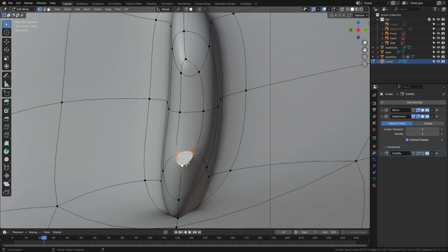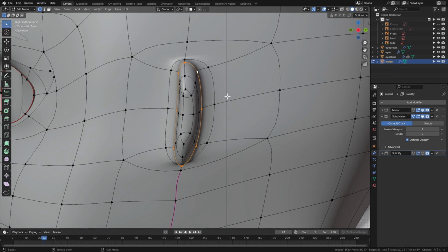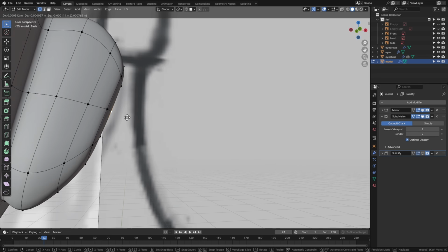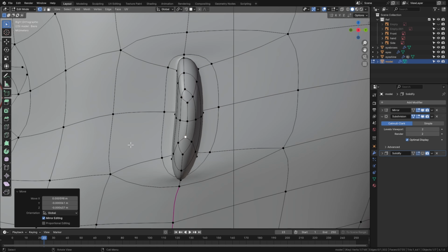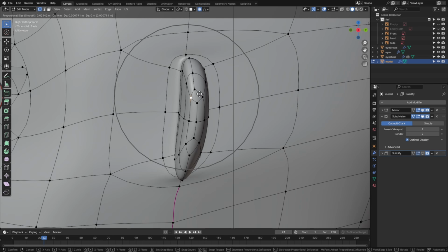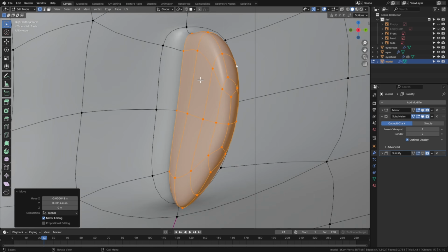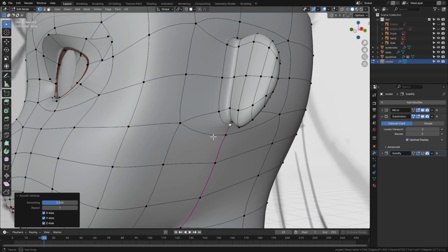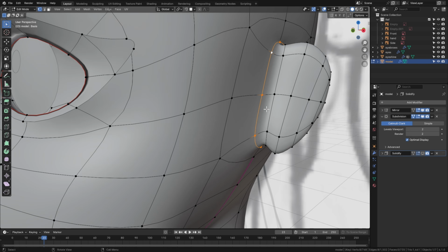With the resulting hole, select the edge loop and extrude and scale down to create the base of the ear loop. Scale on the y-axis or tweak the vertices to shape it around the reference. After that, return to the front view and make a few extrusions out to shape the ear. Close the last loop manually by selecting pairs of vertices and pressing F to fill in faces. Rotate the ear from the top view, face out a little bit as needed.